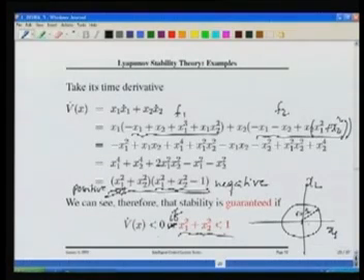So if my initial states are anywhere inside this region, this is always positive, and if this can be made negative, then V dot x is negative definite. Using the Lyapunov direct method, we conclude the system is not globally stable, it is asymptotically stable, and that stability is guaranteed as long as the disturbed initial states lie inside this circle, and the circle has a radius 1, x1 square plus x2 square equal to 1.